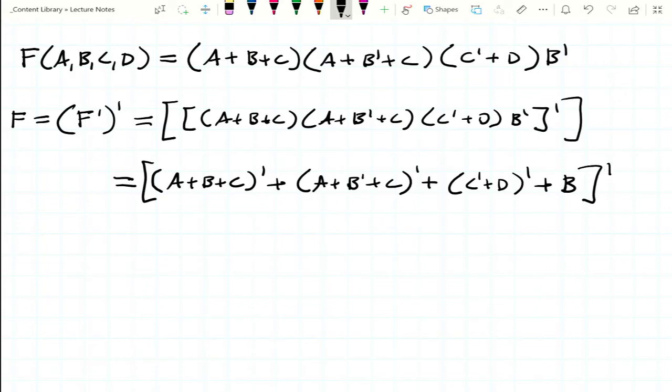So we have a whole operation that consists of all of these ORs that are inverted, that's a NOR, all of these ORs inverted, that's a NOR, and then we have OR this, or that, or that, all of that inverted. So that means our last gate is a NOR, just in the same way we had NAND gates before. That's just to show that the math works out.